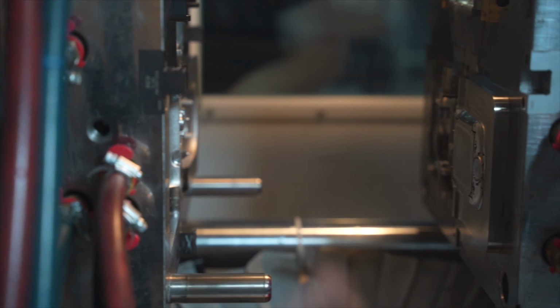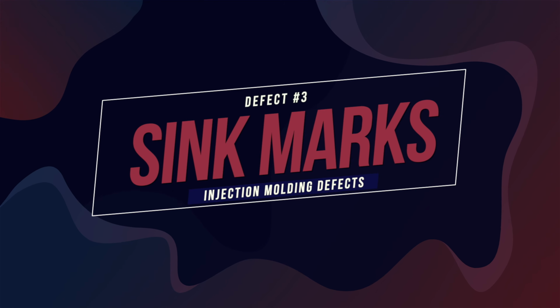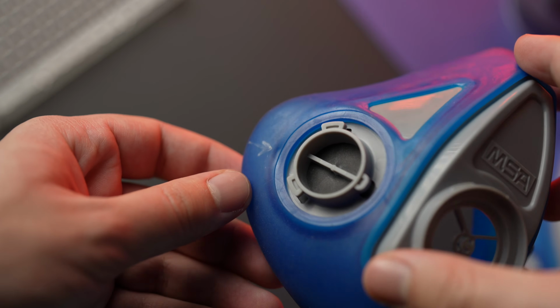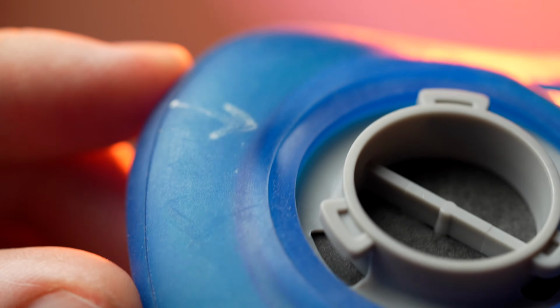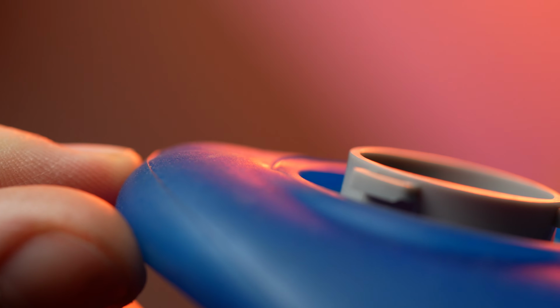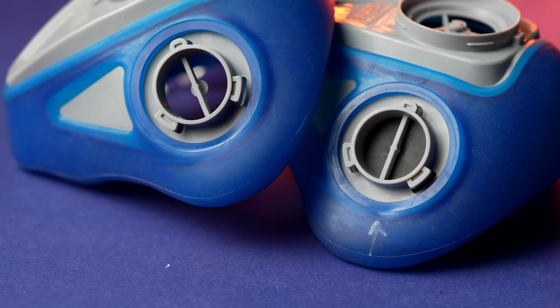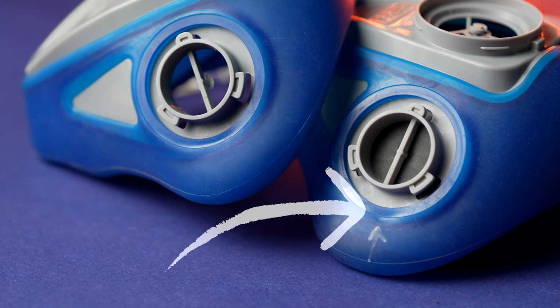Alright, those first two defects are perhaps the most common and easy to spot, but these next few are much more subtle, which is why having an experienced molder in your corner is so important. Sink marks are a localized indentation or depression that appears on the surface of an injection molded part after cooling. Usually you'll find a sink mark along thicker portions of the part where cooling rates can vary significantly. Again, depending on the part's end application, this may not be a huge deal and really is purely aesthetic.